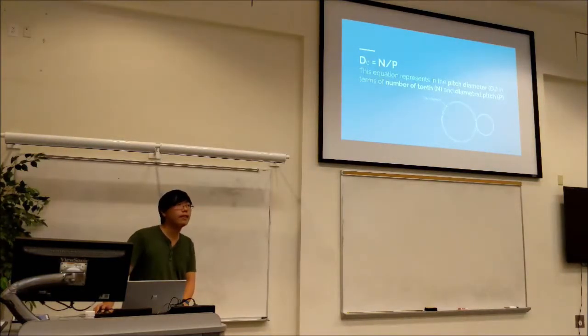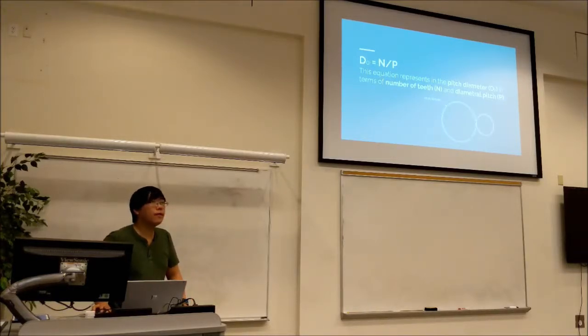Now this is a gear modeling equation. Remember the DP number we were talking about? That's represented as P. This is the pitch circle of the gear, which is where the teeth are meshing. If we have a larger gear and a smaller gear, we have the outer diameter, where the ends of the teeth are, but we also have where they interact, and that's your pitch circle. Your pitch circle diameter is your number of teeth divided by the DP. DP in FRC is normally 20 or 32.